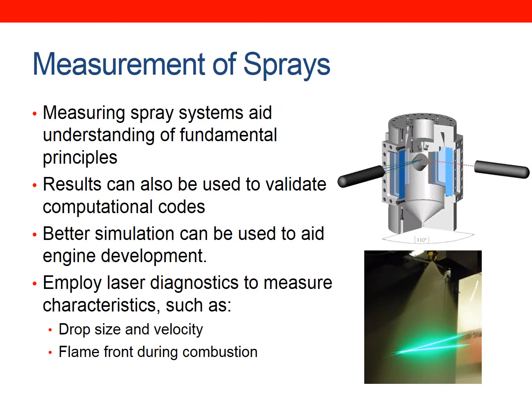So, just taking the point of sprays in particular, there are lots of rigs out there where you can measure sprays in very controlled conditions. This is just a CAD model of one. You can see these lasers pointing in here. These lasers measure particle size, droplet size and velocity, and you can see a picture of the rig here. The results are used to validate computational codes, and laser diagnostics can be used to measure drop size, velocity, and flame fronts.